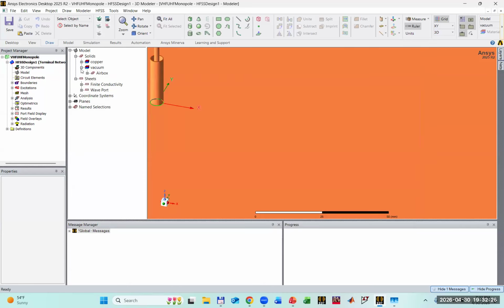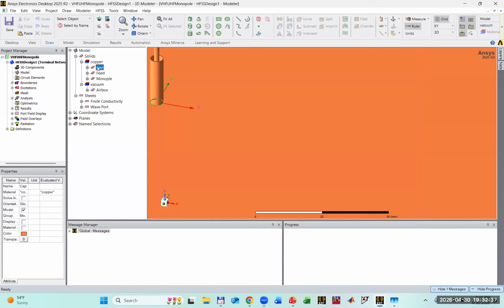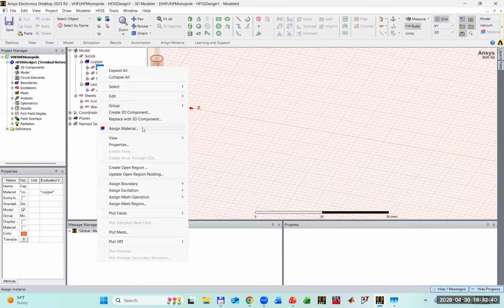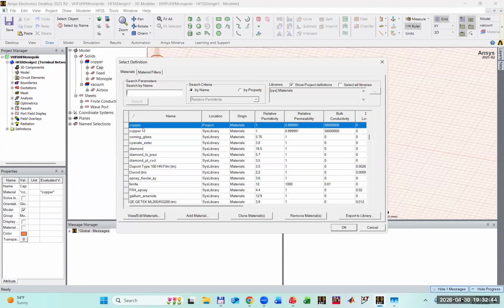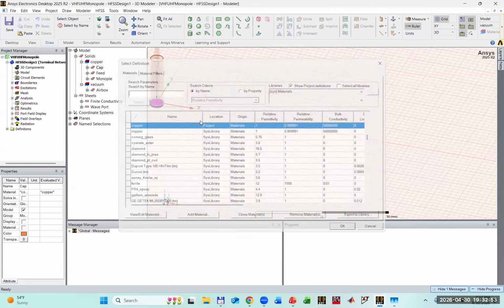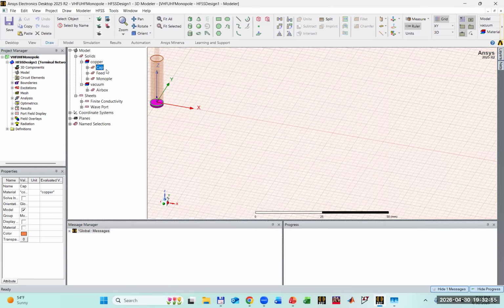Now, you have to define the material properties. Once you create the initial dimensions and geometry, everything is set up as a vacuum. But you can right-click on the material and assign different materials. HFSS, similar to ADS, which I trust some of you have used, has a huge database of materials. Most are there. Unfortunately, not this nitinol wire, but there's a lot of material you can find there.